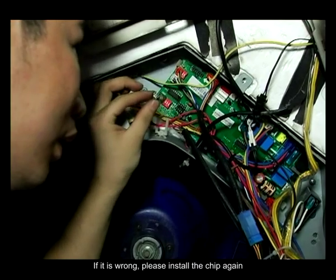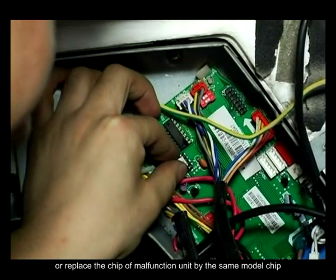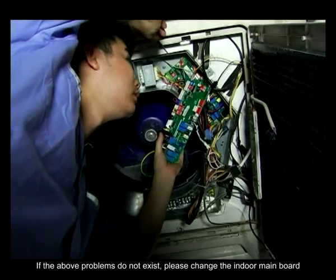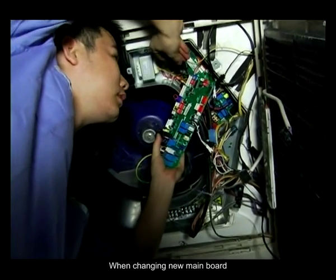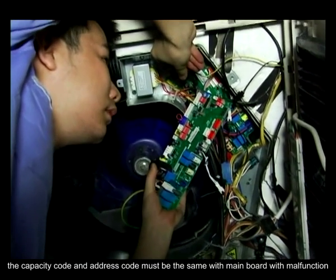If it is wrong, please install the chip again, or replace the chip of malfunction unit by the same model chip in order to confirm if the chip has malfunction. If the above problems do not exist, please change the indoor main board. When changing new main board, the capacity code and address code must be the same with main board with malfunction.